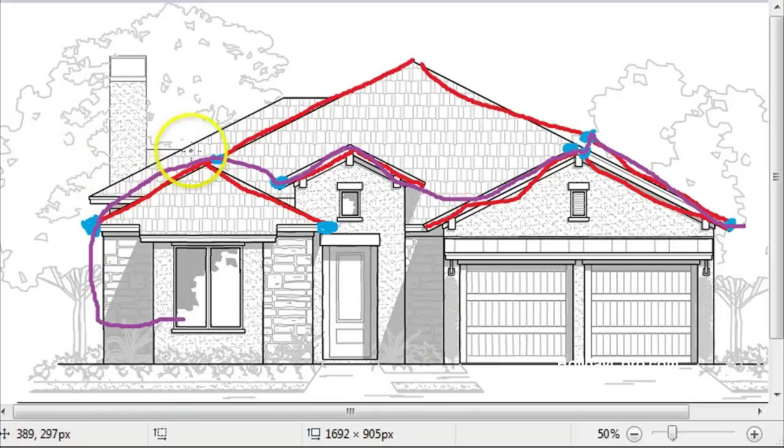Now, what are we looking at in terms of channels? For channels in this design, we would have 3 for this one, 3 for this one, 3 for this one, 3 for this one, 3 for this one, 3 for this one, 3 for this one, and 3 for this one. So we have 1, 2, 3, 4, 5, 6, 7, 8. We have 8 segments, so we only have 24 channels to control for all the segments. Again, we'll only be able to control each segment, not individual parts within each segment, as we can with intelligent RGB. But this is fairly low cost.